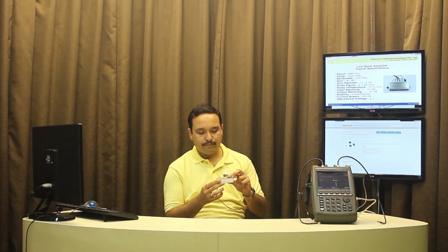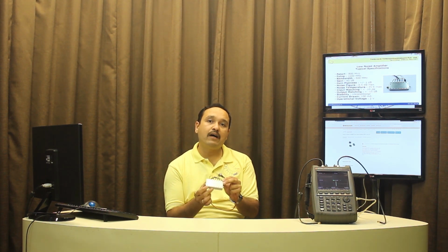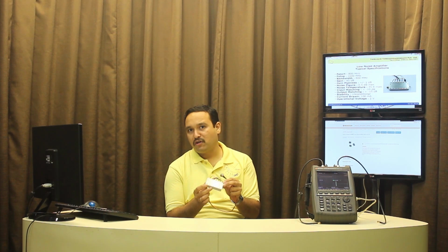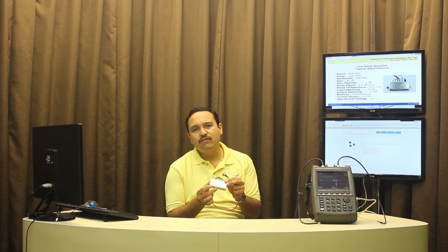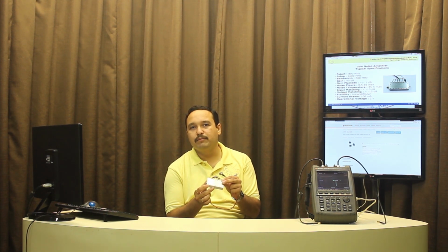It means that the amplifier should amplify the signal without any oscillations. If you design an amplifier which is not unconditionally stable but has better noise temperature, in my opinion it is useless, because it would oscillate and generate a lot of unwanted spurious lines in your spectrum, and it would eventually degrade your signal to noise ratio.